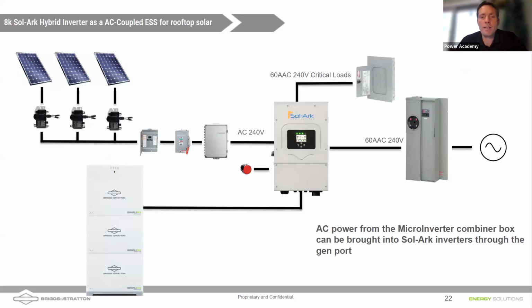Yep, and so we've got AC solar comes on. So now if grid goes down, I think this is labeled as an 8K here, but when grid goes down, right, instead of the solar turning off, this inverter can do what you mentioned earlier, Daniel, grid form, take the power from the batteries, create a grid that's isolated from the main grid, right, to create a microgrid.